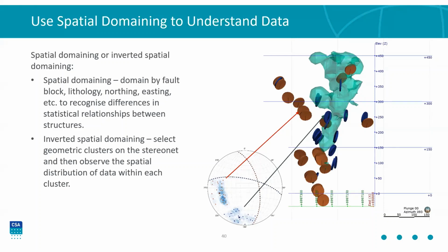So areas where you think structures are similar, and then analyzing your structures in that area as a whole, rather than trying to cover your entire deposit or your entire field area in a single go, because structures do change and move and vary, and so trying to create smaller spatial domains is a really useful tip.